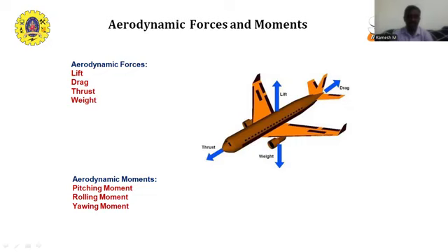That means people, baggage, freight, etc. The weight is distributed throughout the airplane, but we can often think of it as collected and acting through a single point called the center of gravity. In flight, the airplane rotates about the center of gravity.